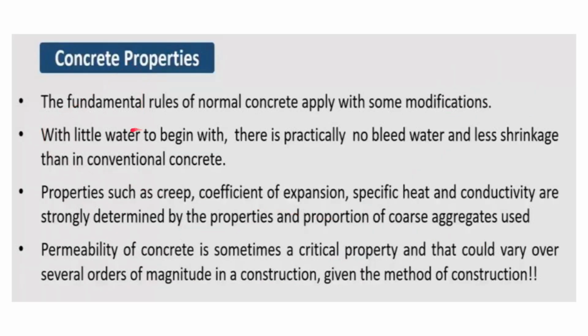So concrete properties: the fundamental rules of normal concrete apply with some modifications. With little water to begin with, there is practically no bleed water and less shrinkage than in conventional concrete. So properties such as creep, coefficient of expansion, specific heat and conductivity are strongly determined by the properties and proportion of coarse aggregates used, because they occupy 70 to 80% of volume.